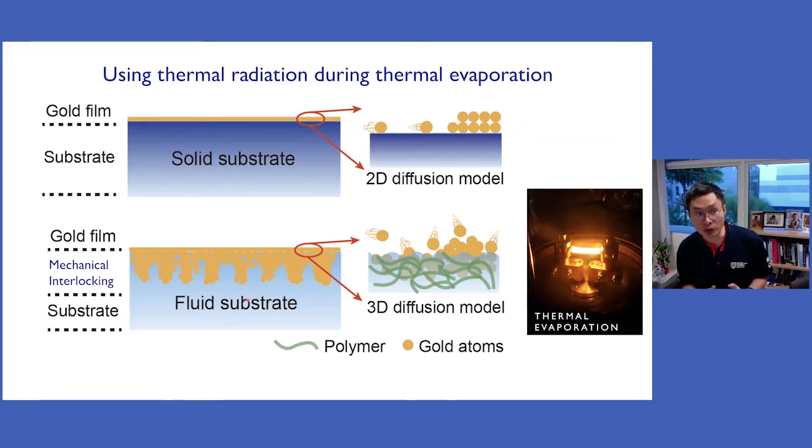It's a well-known material. For PDMS, we already know we can control the curing time. We can control the cross-linking inside, and also we can control the amount of polymerization. Now of course, how do we do it? First, we use a substrate of half-cured PDMS. It means there is still 50% monomer inside.